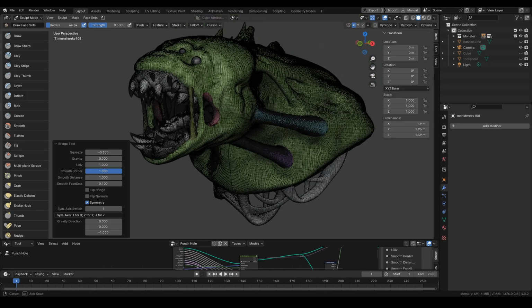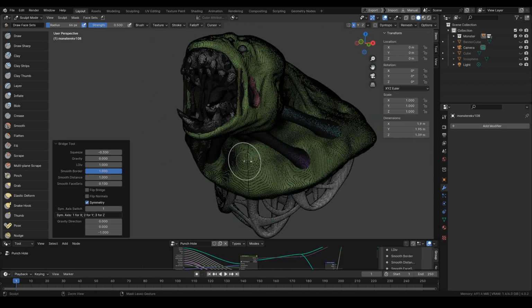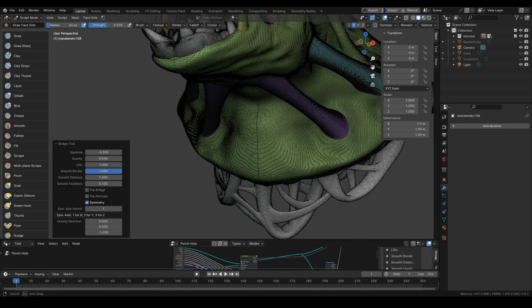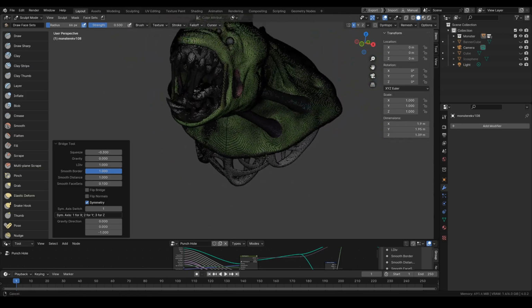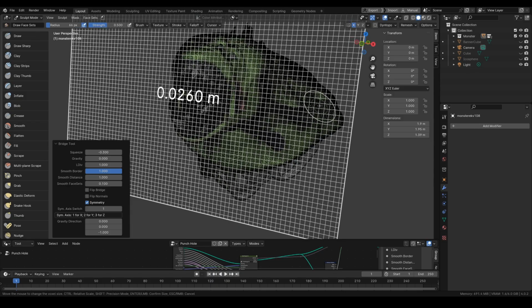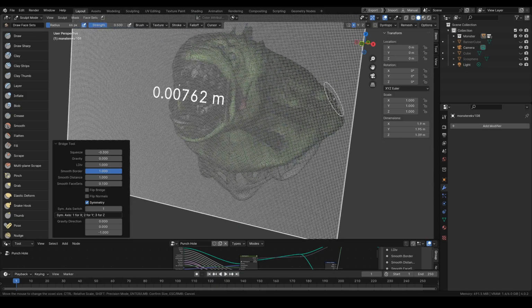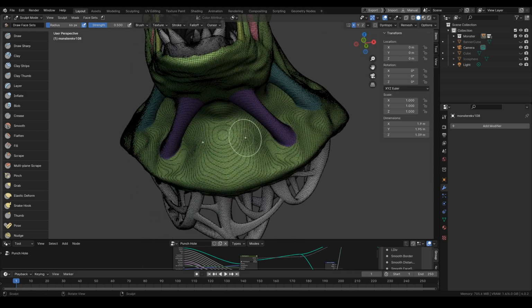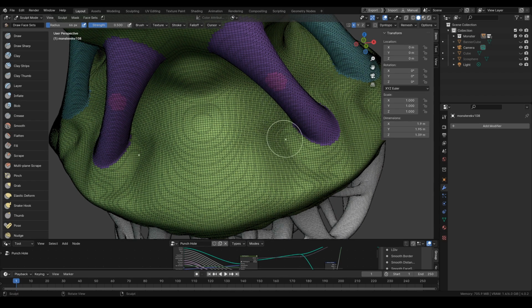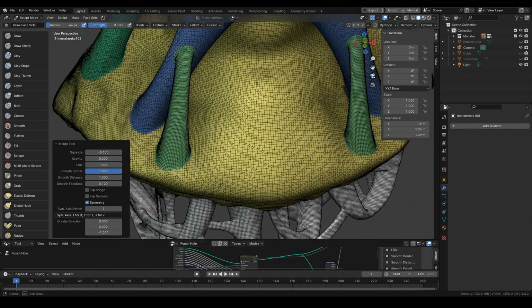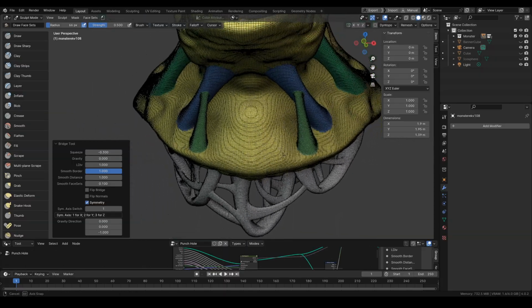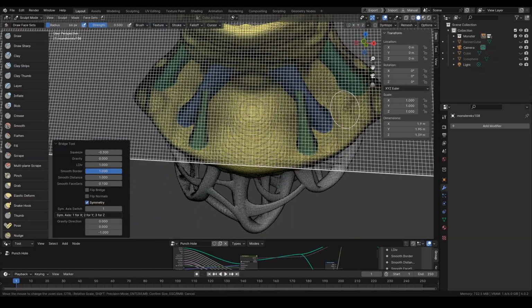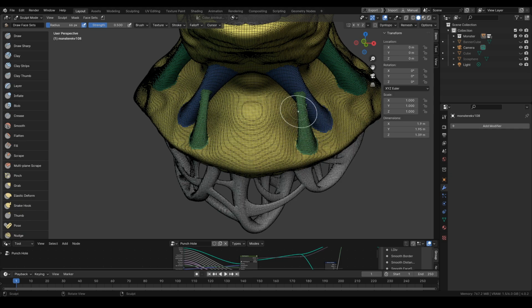One more thing I would like to show you is that using symmetry needs an exactly symmetrical mesh. When that's not the case, then some kind of bugs might appear. Let's say in that case, I just did a remesh with the symmetry turned off, and for now it works fine, but let's do it a second time, and let's create another bridge.